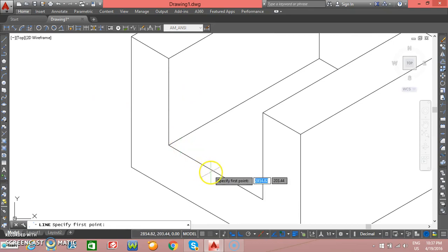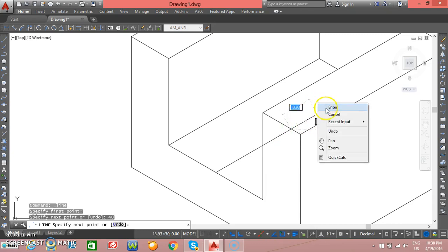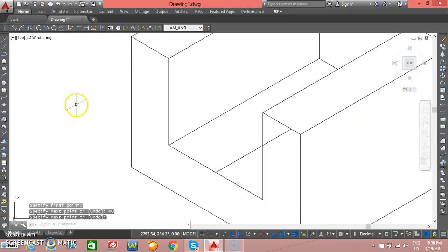Okay. When you bring the cursor here, you must get the midpoint. Yeah, that is the midpoint. And in the iso right plane a distance of 40 millimeters. So that end of that line will be the center for the ellipse.